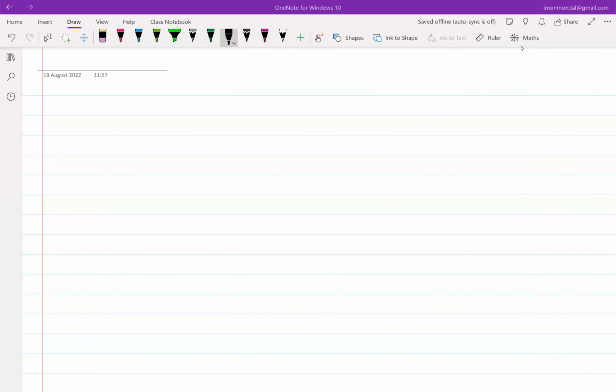So what I want to do now is to draw your attention to the fact that when we did particularly a voltage control voltage source, we made one simplistic assumption that a voltage control voltage source is nothing but V naught equal to K times Vi, where K can be anything. But the realization that we did was for a particular case of K equal to 1. The aim of this course is to essentially design VCVS, but not with a gain of K equal to 1. It can be anything. That's what we would like to see here. The framework of what we need to do has already been laid. We'll formalize it and see how to proceed along those lines.